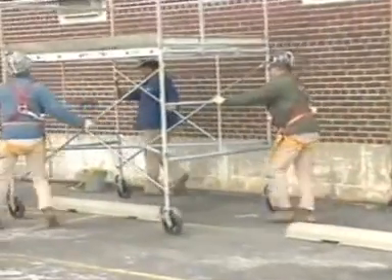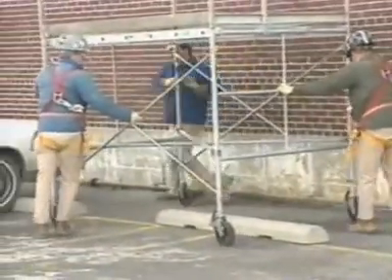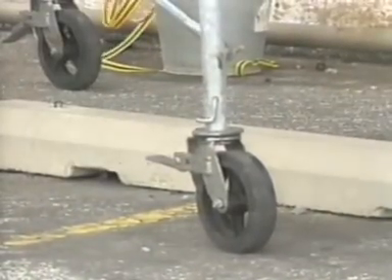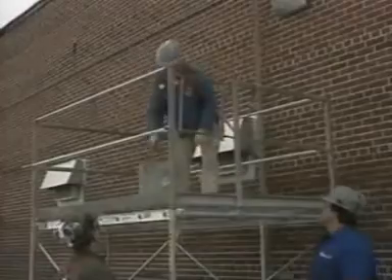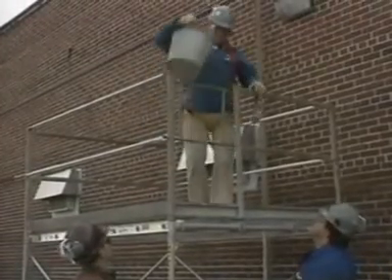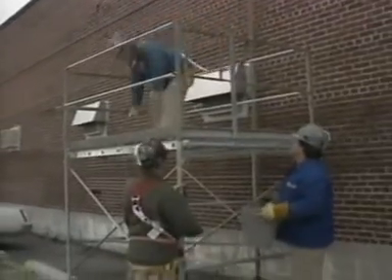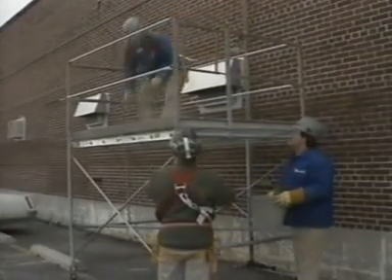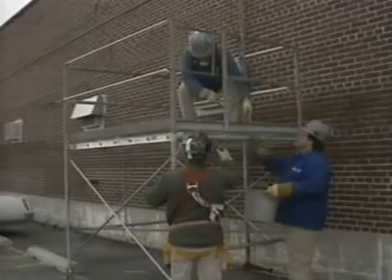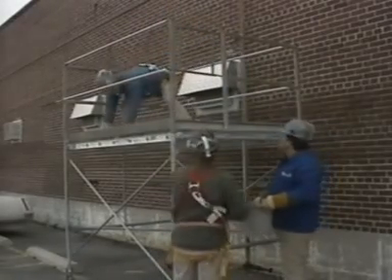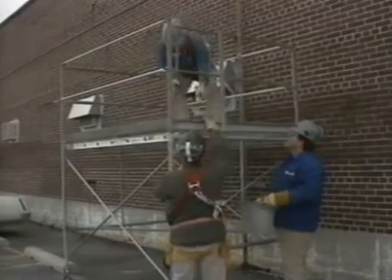Rolling or mobile scaffolds can only be used on level surfaces, and all wheels must have a positive lock to prevent unexpected movement. As we discussed earlier, staying on board a scaffold while it is being moved can have tragic results. To prevent struck-from-above accidents, the scaffold should also be cleared of all unattached items prior to its relocation.